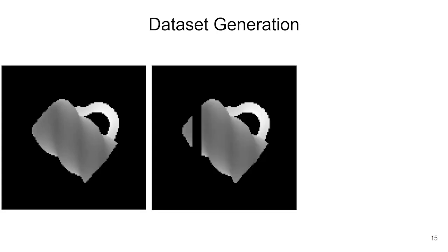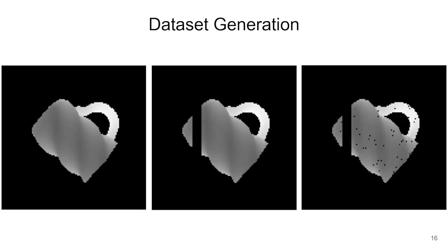To train the CNN to estimate the rotation difference, we first need a dataset. We generate a dataset of images in simulation using the Python library PyRender. However, these smooth depth images are perfect renderings, so we do some image processing. We make the network robust to occlusions by generating random cuts on the image. We also zero out random pixels to further improve robustness.